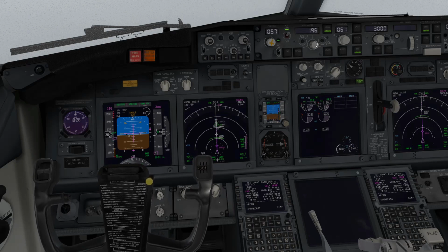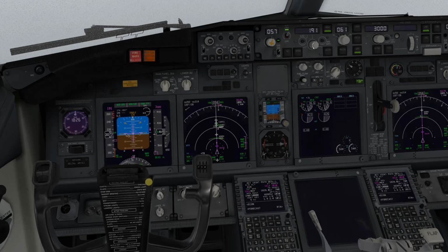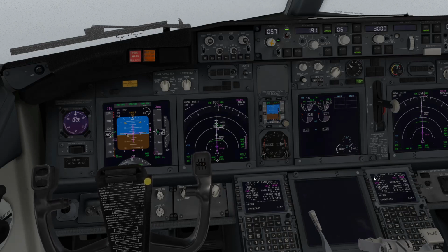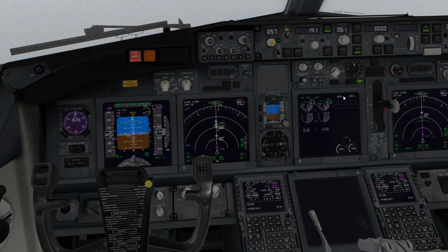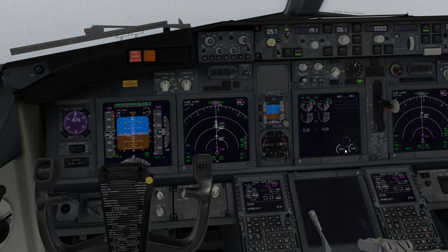And you can set it to whatever you like. I'll keep bugging back to my maneuvering speeds though. We can also drop down flap 5 now, a little extra drag out so the aircraft can start slowing down.